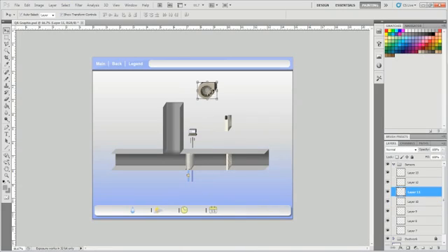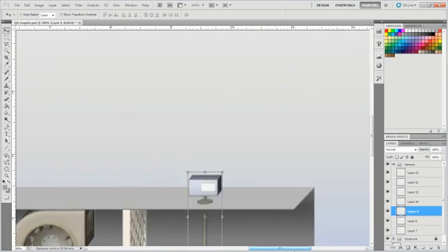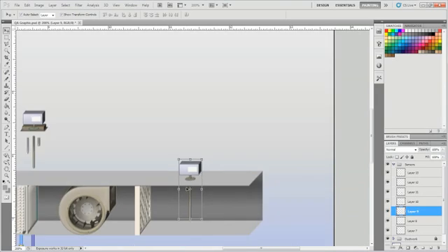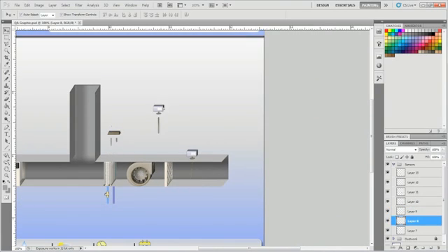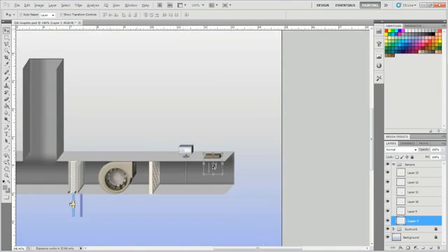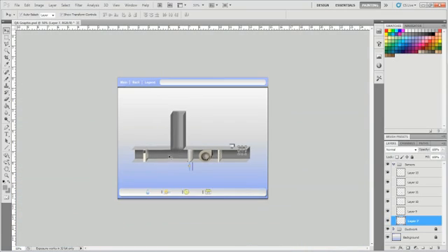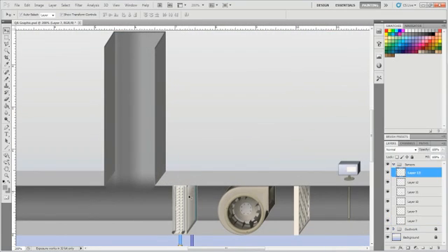And as you position them, sometimes you might need to get a little bit better look to make sure they're lined up correctly. So zooming in might be a good idea. You can use Control and plus to zoom in, and Control and minus to zoom out. Or you can just hold Alt as you turn the scroll wheel on your mouse. And sometimes you may want to turn the sensors on or off. You can do this by toggling the visible button on the folder.